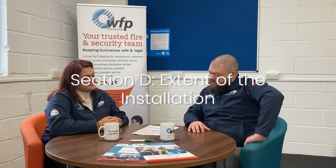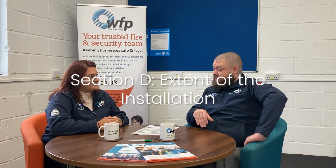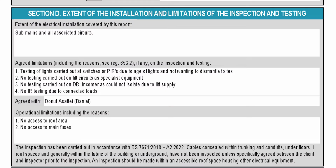So that's section C. Section D, really important, this one, because it talks about the extent of the installation and the limitations of the inspection and testing. So why is that important? For instance, on this one, the extent of the electrical installation covered by the report is the sub-mains and all associated circuits, or 100% of the installation, pretty much. So we're testing absolutely everything, but we agreed limitations. On this example report, we put that the testing of the lights was carried out at the switches instead of the lights, because the lights were so old we didn't want to dismantle them. We could take them apart and then they don't work again, and it's a nightmare, so we tested from the switch instead. So that's an agreed limitation.